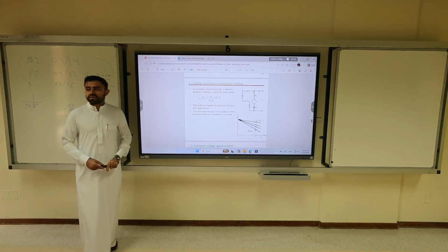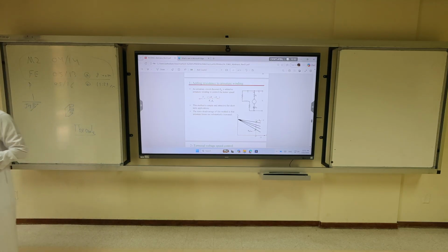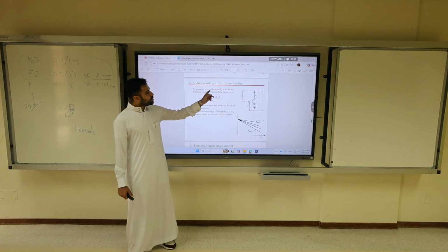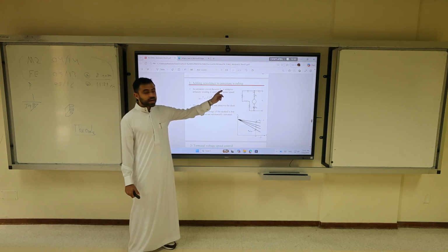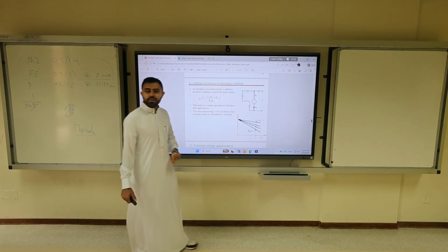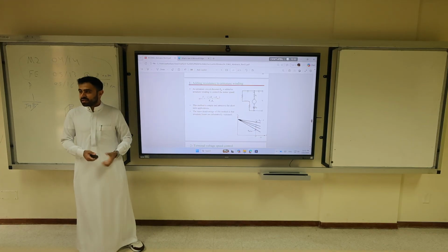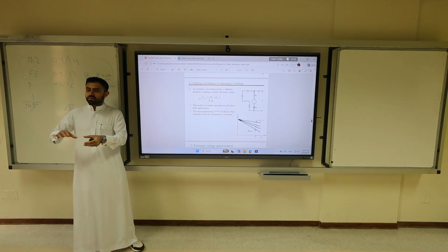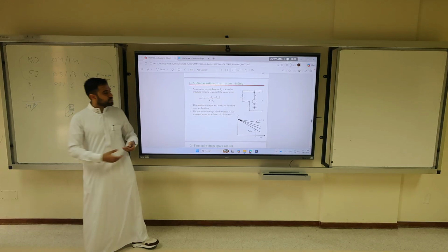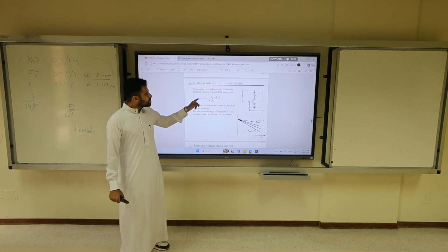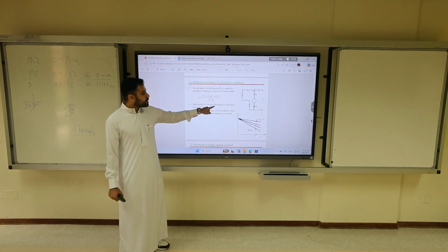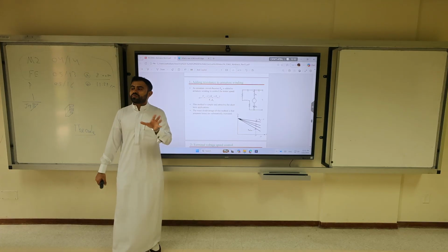Now let's talk about the first approach, adding resistance. If you add a resistance to the armature circuit, it's called a rheostat. A rheostat is the variable resistance that, if you tune it, you can control the speed. Instead of adding a fixed series resistance, you supply the motor with a variable resistor, and then you change it until you reach the speed that you want. So this is the equation of omega. This method is simple, and it's only used for short durations.